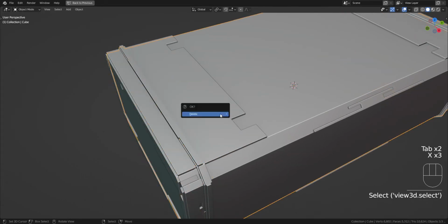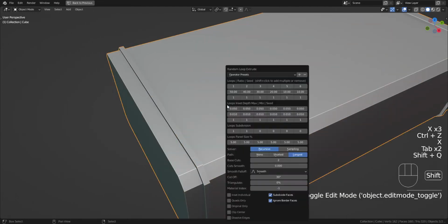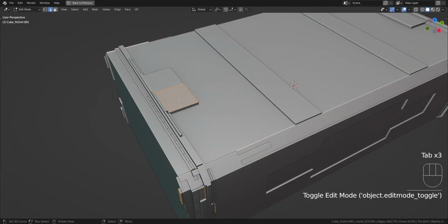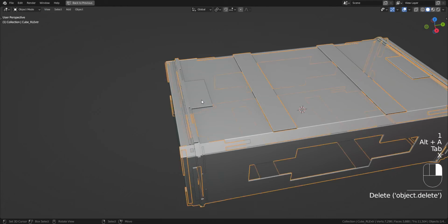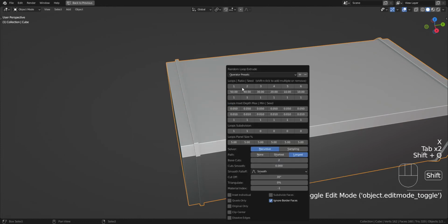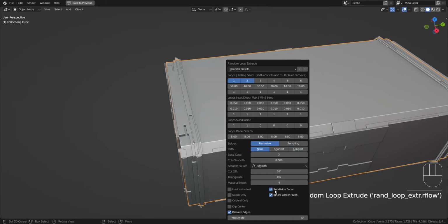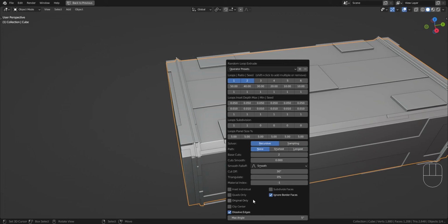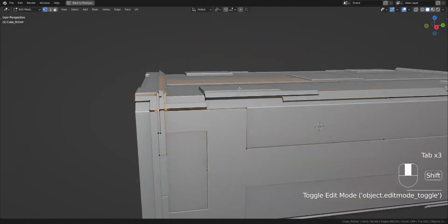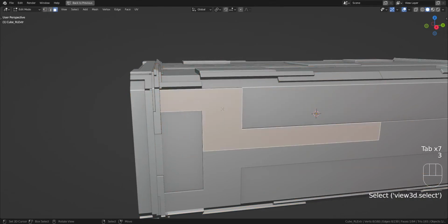However, if you have subdivide faces off, then you're better off using the limited dissolve to get rid of the useless verts. So with limited dissolve on or dissolve edges on, which is using limited dissolve, it gets rid of the vertices depending on the face angle, and you'd have ngons.